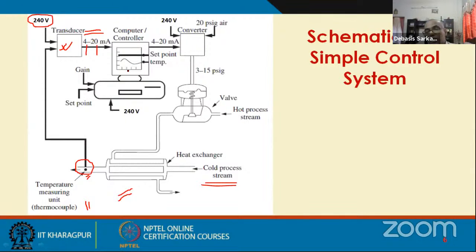If I'm talking about a digital control system, most likely the controller is a computer. So this computer also needs an auxiliary power source, say 240 volt. So in this controller, you can specify the set point. Like you have seen in the previous slide, remember the role of the comparator. Now, in this computer, you can actually write a program for, say, a proportional controller.